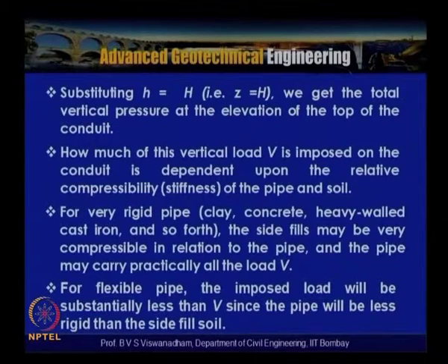So we have understood now that for very rigid pipes, the side fills may be very compressible in relation to the pipe, and the pipe may carry practically all the load, and the type of arching that comes into picture here is passive arching. In case of flexible pipes the imposed load will be substantially less than V, since the pipe will be less rigid than the side fill soils. So that is the active arching phenomenon.